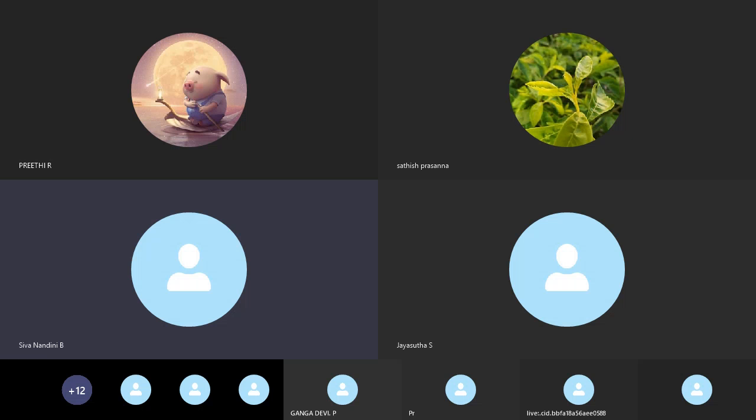D2 1 represents pin number 1 of diode 2, which is connected with pin number 2 of R2. R2 2 represents pin number 2 of R2. So the connection is made between pin number 1 of D2 and pin number 2 of the resistor. This you can check in slide number 15.